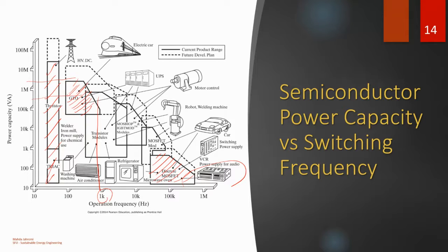Yes. So what I mentioned in our last lecture was that switching frequency determines the harmonics. The higher the switching frequency, the higher will be the frequency of your harmonics. And if your harmonics are at a higher frequency, it's easier and cheaper to filter them than if they're close to your actual frequency. For example, if you have a waveform that looks like this, a sine wave that has a high frequency hash on it, that's really easy to filter.